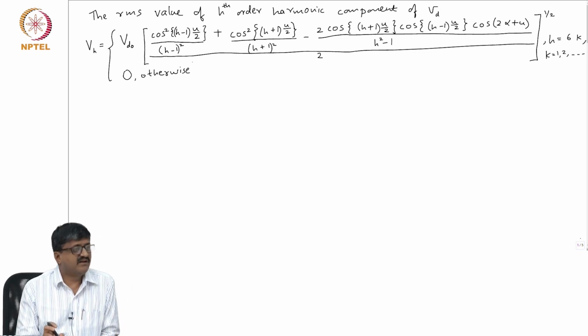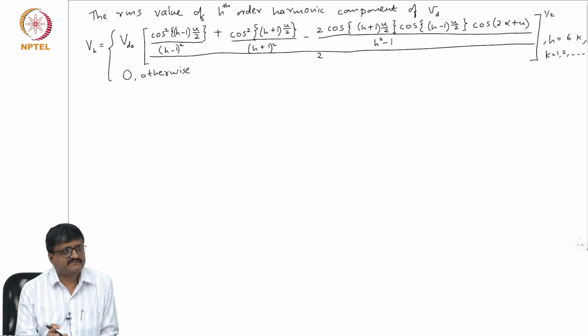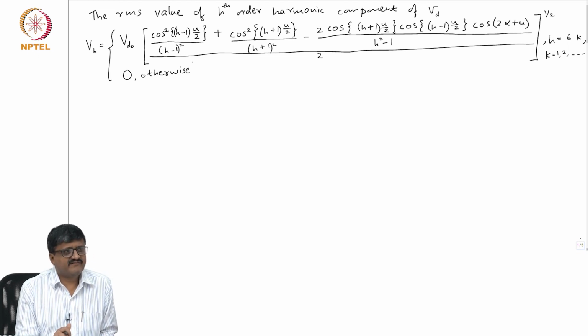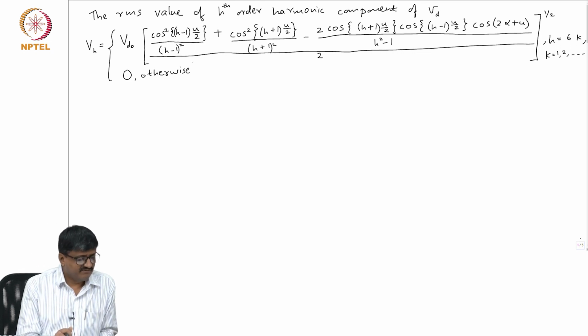Here we have 2 subintervals in each interval. That means if there are 6 intervals and 2 subintervals in each interval, in one cycle we have 12 subintervals. So, we will form a table as in the case of zero overlap angle.